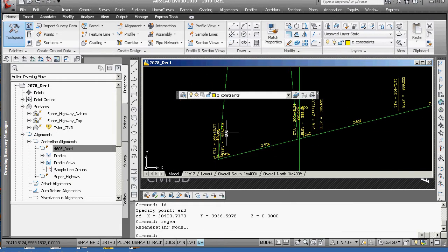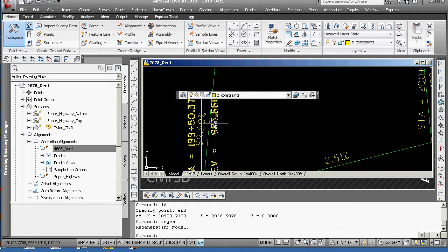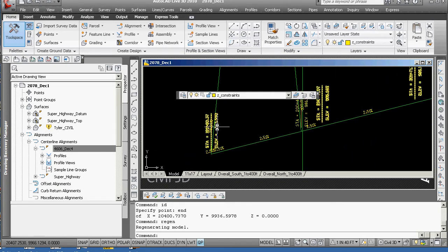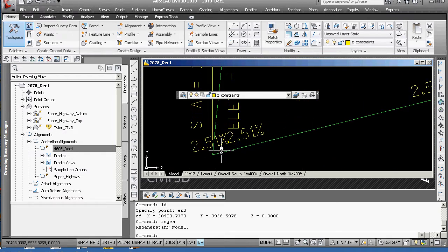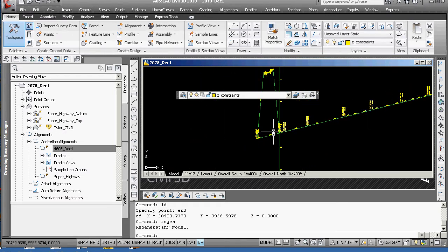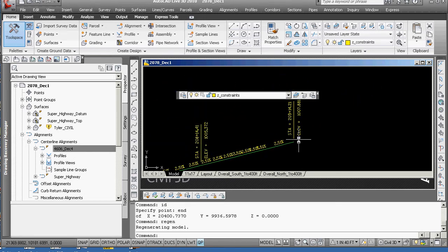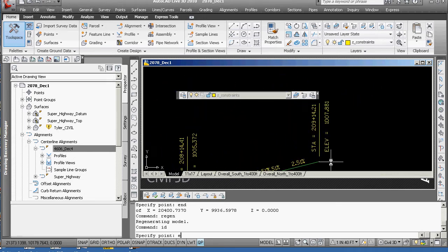And if you notice there, that label is telling you that it's supposed to be a certain elevation and it in fact is not. So we're going to try one more. Right here on the end is a reasonable one. ID, the end point of that. 213.645837, and it's supposed to be 1017, and you're off by 1,000 up and down. So somehow, it should be 1007, so you're off by 100.